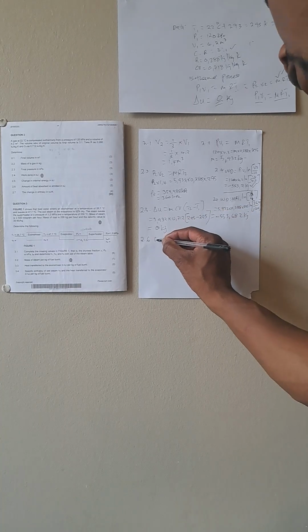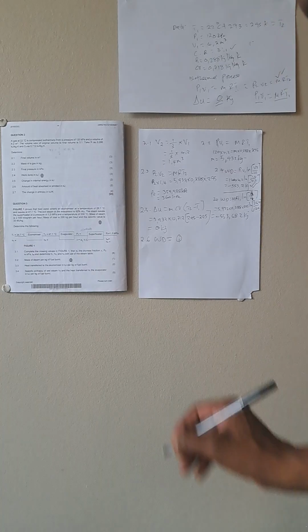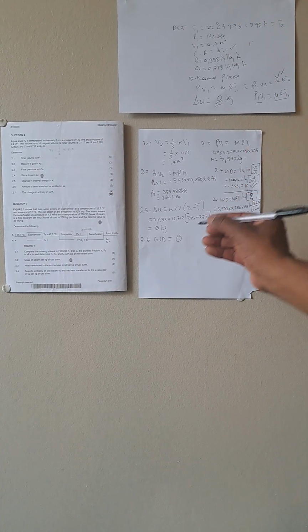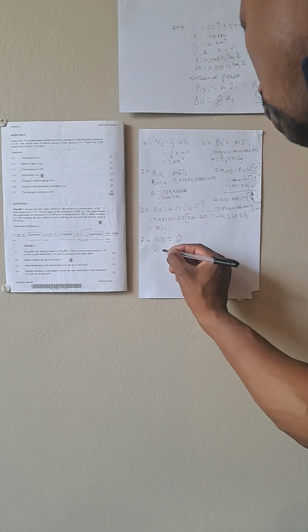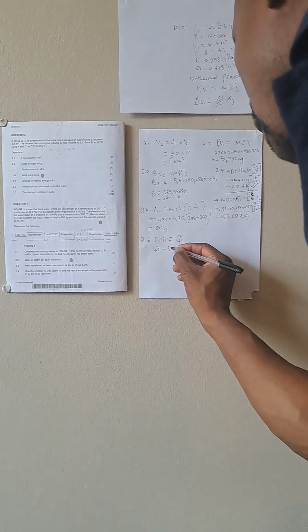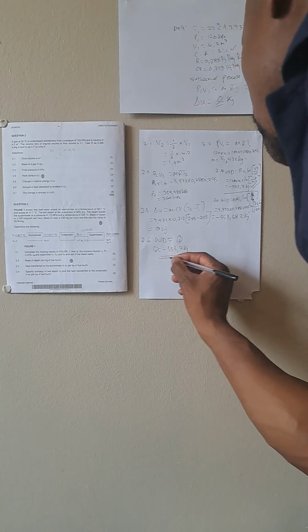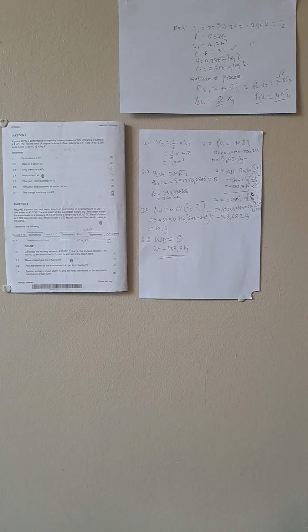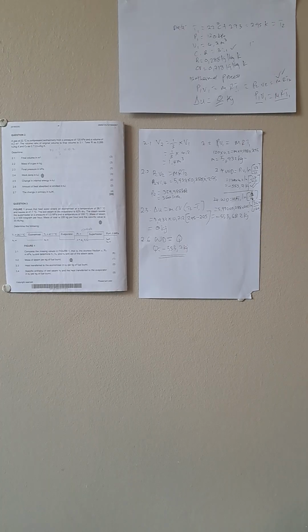We simply say, remember, work done during an isothermal process equals our Q. Therefore, Q equals minus 553.7 kilojoules. It shares the same units, so it shows that indeed this energy was lost. It was not gained, because our sign here gave us a negative sign.